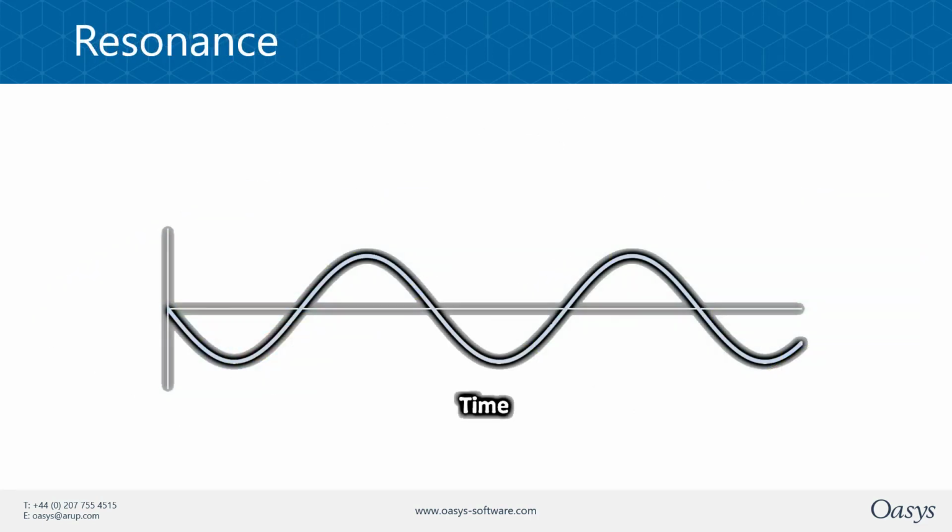Now, I mentioned resonance. What is resonance? This is when the vibrations build up over time. Take an example where a floor vibrates with a particular frequency. If that frequency is the same as the walking speed, each footstep will push the floor more and more, increasing its amplitude and acceleration. This is called the first harmonic, when the footsteps are totally in sync with the floor.